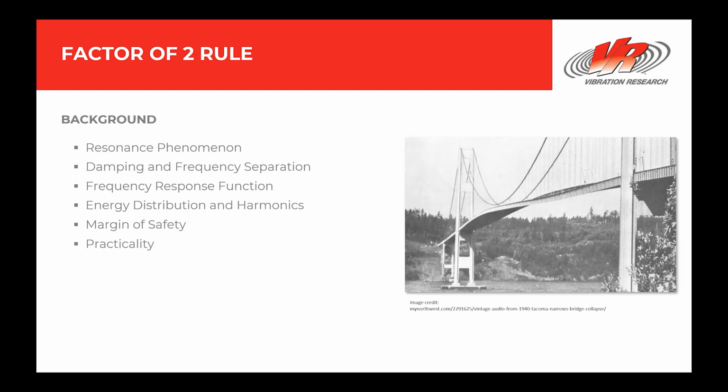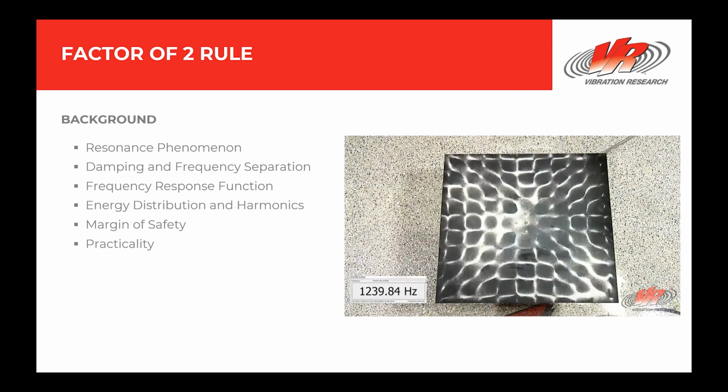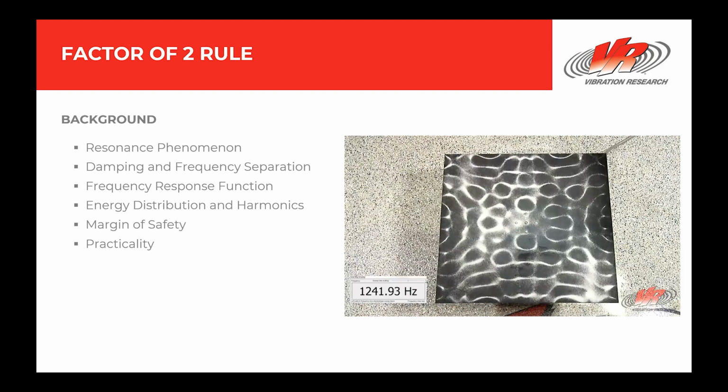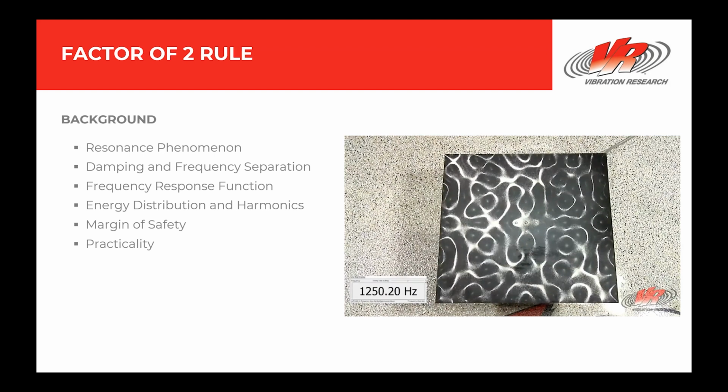The response of a system to a dynamic load is characterized by its frequency response function, or FRF. The frequency response function is a mathematical tool used to describe how a system responds to different frequencies of input. It shows the relationship between the input frequency and the output amplitude and phase, indicating how effectively the system transmits different frequencies. Around the natural frequency, the response is significantly higher. We'll look at the equations behind this in a moment.